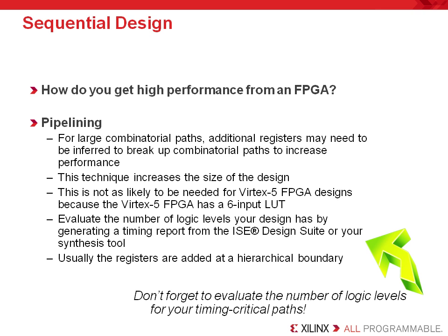And if you need to add registers, consider pipelining the outputs of a purely combinatorial path or the outputs of a hierarchical boundary. In the end, these techniques are the simplest way to make an effective design change to improve the speed of your design.